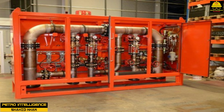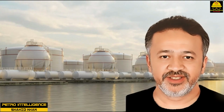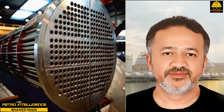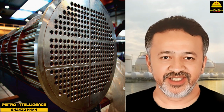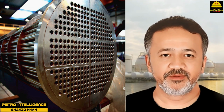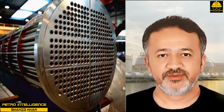Brasses are widely used because of their resistance to corrosion from water containing various impurities that are corrosive to steel. They are weaker than steel and lose much of their strength when heated. They are not normally used at temperatures above 450 degrees Fahrenheit or 232.22 degrees Celsius. Brass is most commonly used in condenser or cooler tubing when water is the cooling medium.